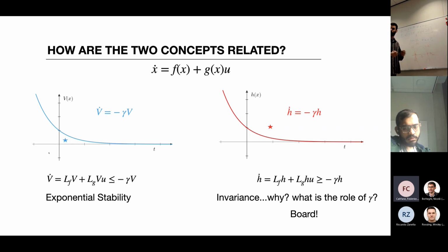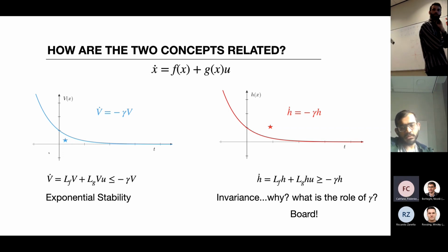No? Instead, if the gamma is low, you start to impose a condition on the CBF before actually going to the boundary of the safe set. You start to push the system back before. That's what the gamma represents. It's the influence of the barrier function, exactly. I mean, the barrier function, you design it to encode the safe set. And if you apply it in Nagumo's way, then the controller really does something only at the boundary, pushes you back hard at the boundary.